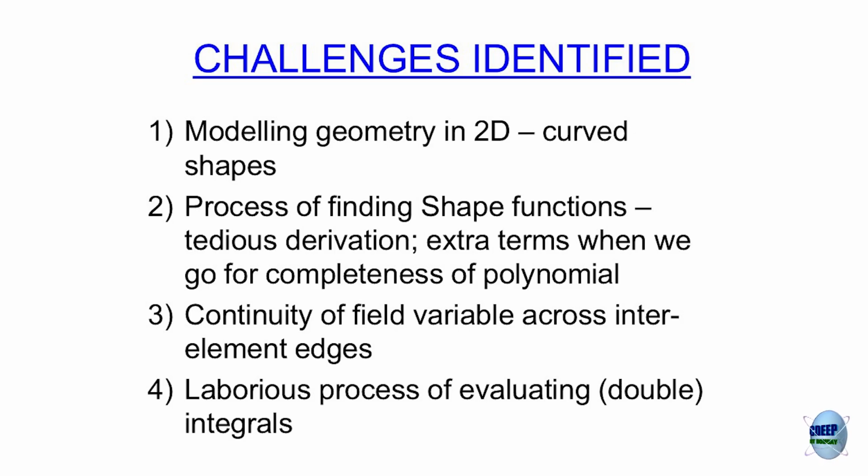So if you look at this as an advantage, the disadvantage we had is that I am interested in the derivatives in xy coordinates, but now everything is in terms of zeta eta coordinates or L1, L2, L3 coordinates. So I will need to relate these derivatives to those derivatives. So in between, a lot of maths came in, Jacobian came in. So there is an extra penalty we have to pay there. So somewhere we gain something, somewhere we lose something.